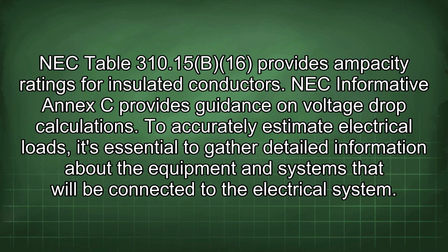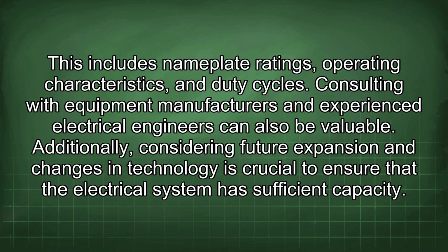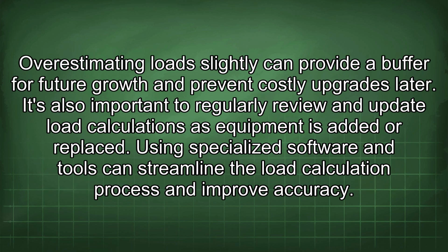To accurately estimate electrical loads, it's essential to gather detailed information about the equipment and systems that will be connected to the electrical system. This includes nameplate ratings, operating characteristics, and duty cycles. Consulting with equipment manufacturers and experienced electrical engineers can also be valuable. Additionally, considering future expansion and changes in technology is crucial to ensure that the electrical system has sufficient capacity. Overestimating loads slightly can provide a buffer for future growth and prevent costly upgrades later.